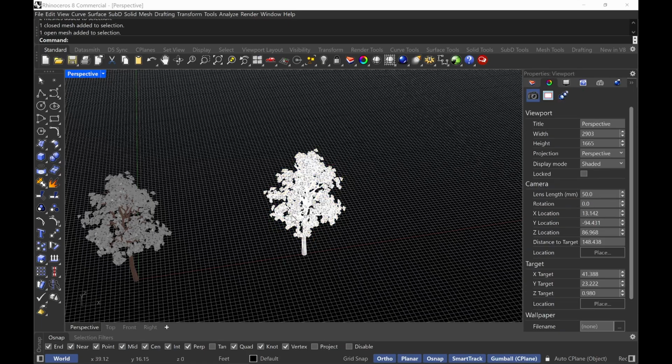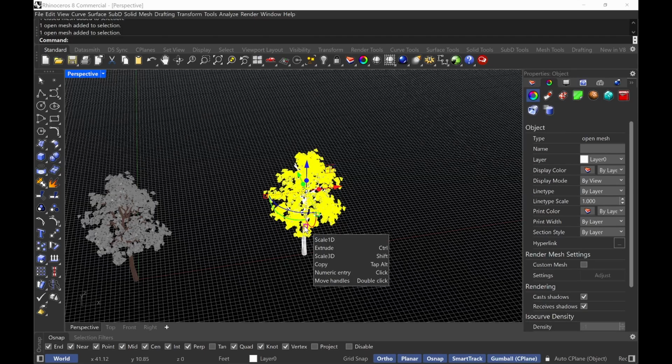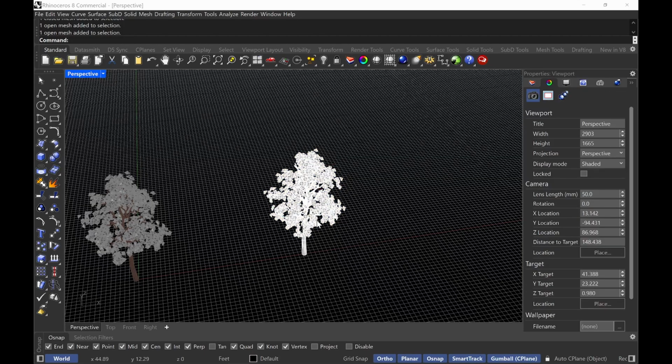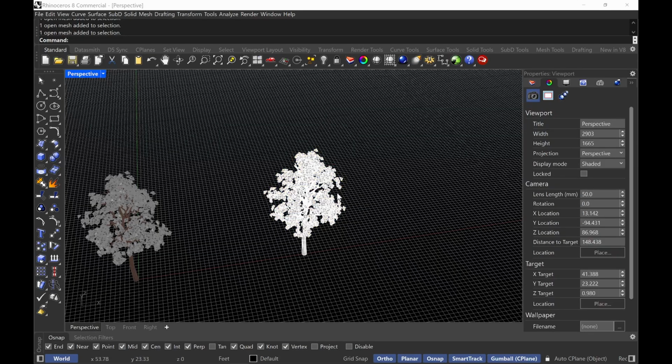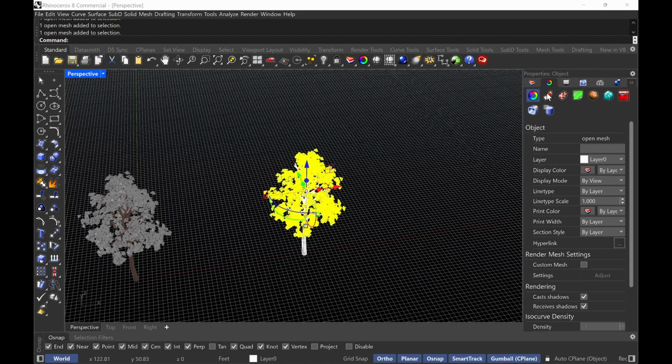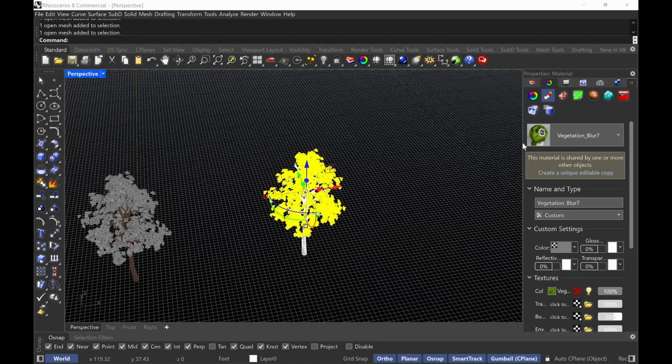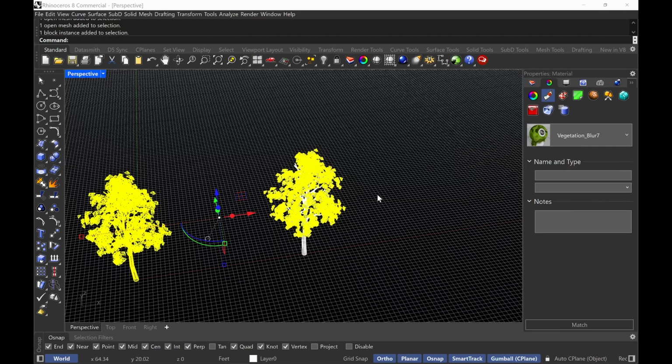But sometimes you'll have blocks where they're not grouped, okay? So this specific block that I downloaded, the elements were grouped together already, which is nice. But sometimes they won't be grouped. Even in the import options, when you group it by texture, it won't do it. And if that's the case, a quick workaround is if you click on the object and go to your properties and go to material, like for example, this is on this material here, right? I can just right click and do select objects, right? And that will help you quickly filter things and you can group them together or join them as meshes and then assign it to the layer that you want. So that's important to understand.